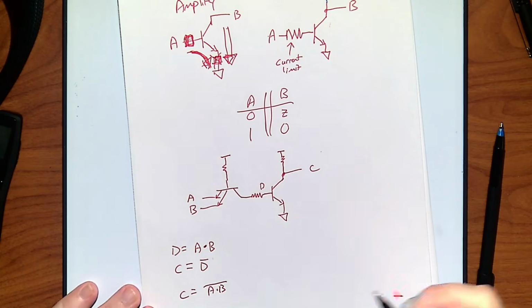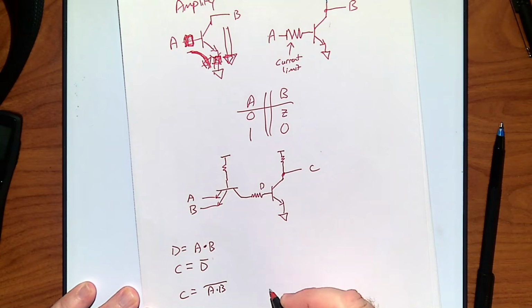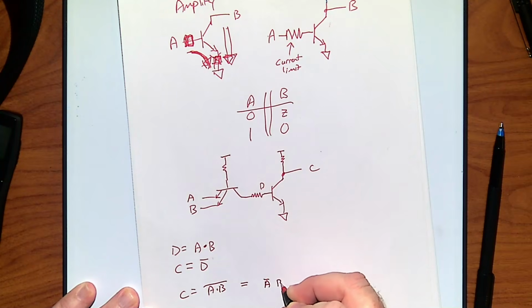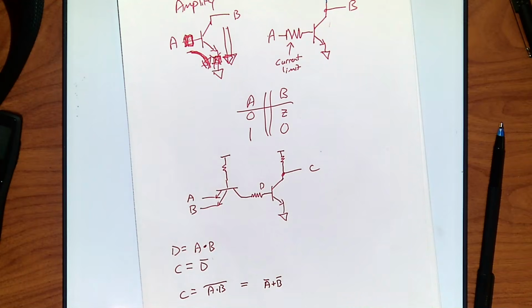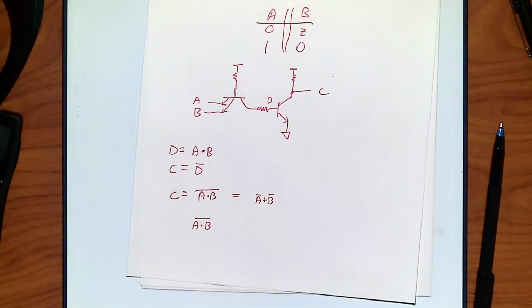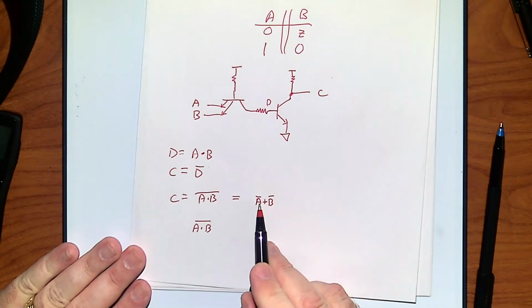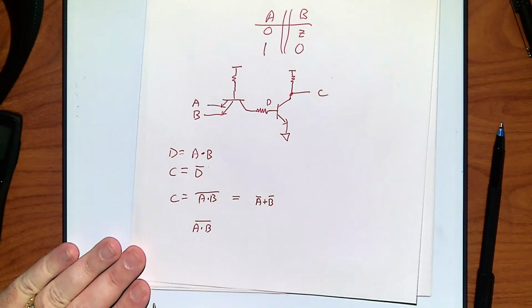So we know that this, if you remember, is the equivalent of you flip the inputs, you flip the gate, and you flip the output. So this has to be this. So it's an inverted OR one. So I could therefore take, if I did a NAND gate into a NAND gate, I could do the first one in this form. I could do the first one kind of like this, and I could use that as the input into one gate of the next.